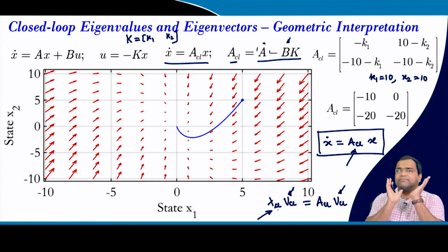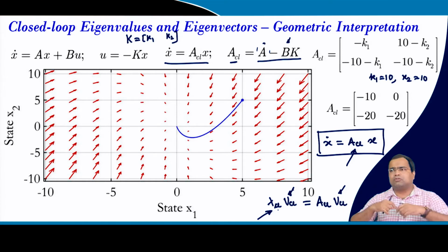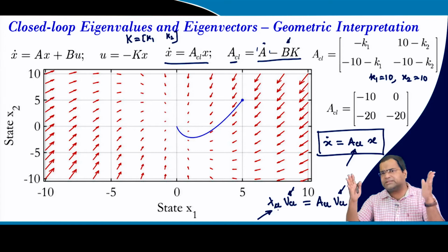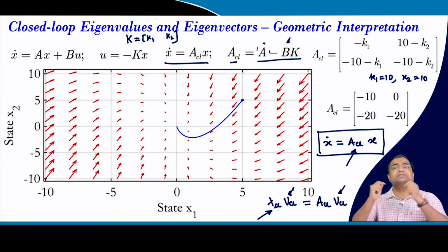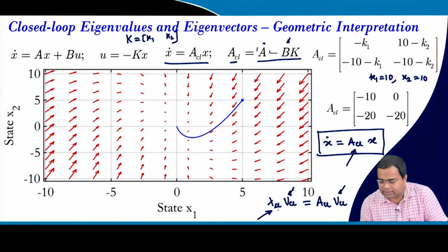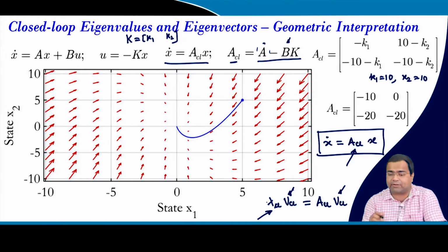But in this case, in state feedback control, we generally talk in terms of eigenvalues. In the closed loop eigenvalue, we can choose based on where we want to place the eigenvalue, because it will indicate our closed loop performance. That means what will be my transient, overshoot, undershoot, etc. The specification can come from time domain specification and so on. But we can place the closed loop pole, and accordingly we can design this gain matrix.